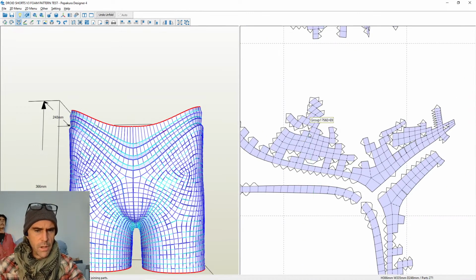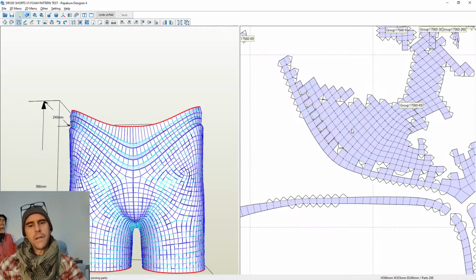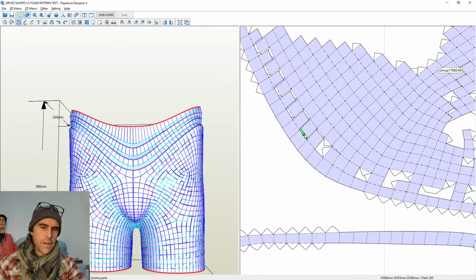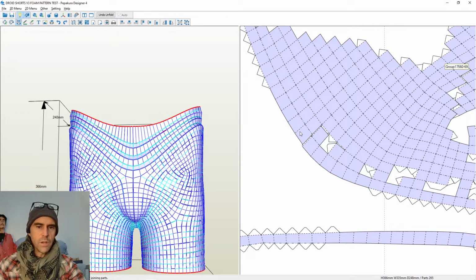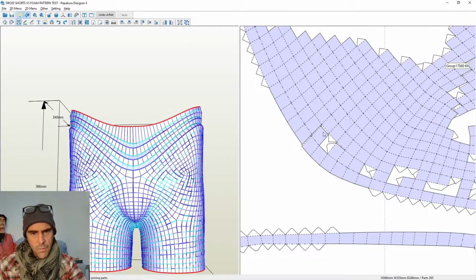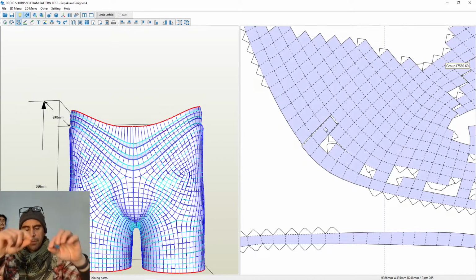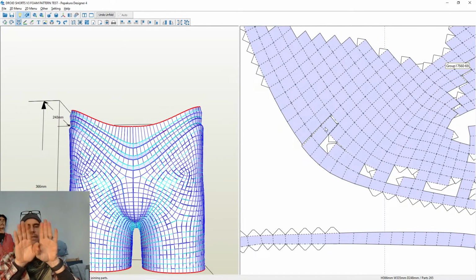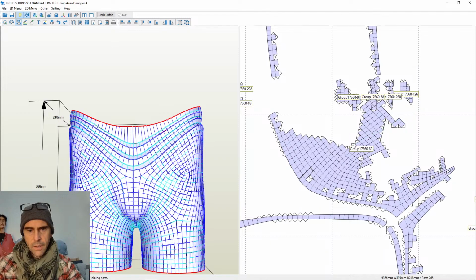But anyway, let's see here. We'll start connecting pieces. You can see as I do this, it'll start patching these little holes and it'll start to come together. A lot of individual polygons are separate, but with this one here, where these guys are really close, if I do this, it's just going to move it to the other side. It's going to keep popping it apart, which we don't want. I guess it's close enough, but somewhere in here I'm going to have to put a relief line where it splits. In a pattern, that'll be something where you cut it and then glue the pieces together, and that'll force a curve into the foam, which is something we want.